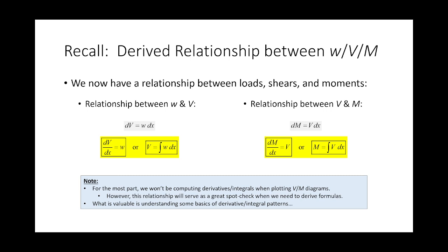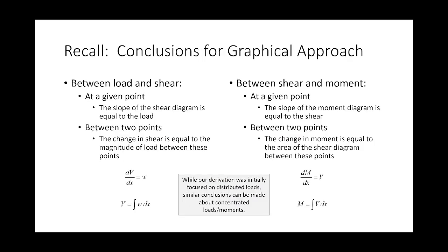If you know how to draw a shear and moment diagram for distributed loads, concentrated loads, triangular loads, internal hinges, fixed supports, you name it, adding the concept of a frame, like saying we're going to draw shear and moment diagrams for frames instead of beams, there is nothing theoretically complicated about it. There's nothing about it that makes it any different, okay?